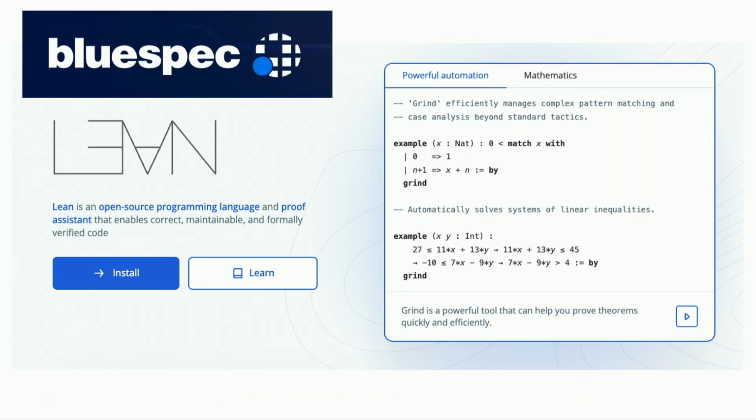And I think what we should do is build up a library in Lean for hardware design, but we should not base it on the batshit crazy semantics of SystemVerilog. We should not base it on Mealy-Moore machines, the machine-coded sequential circuits, or Kripke structures that are used for model checking. We should base it on a sensible semantics for circuit design, which has been proven to work. So I think we should take Bluespec's semantics and code them up as a library in Lean, and use that as a basis of how to design hardware, verify hardware, do proofs, and do implementations.